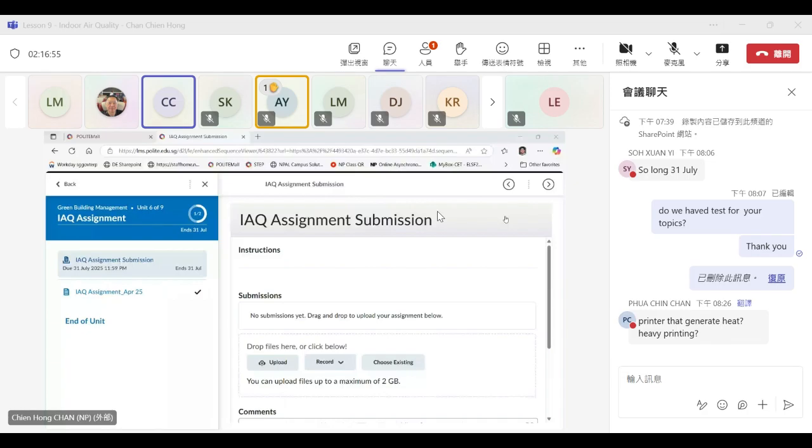I see. Yeah. So of course, as I mentioned, when you need to solve condensation issues that result in mold, there are 2 very important things that you need to consider. What is making that surface so cold, and what is the source of this slightly warmer and moist air? If you can find either one of these, you have a better chance of finding the cause of the condensation. Then you can solve the mold issue.